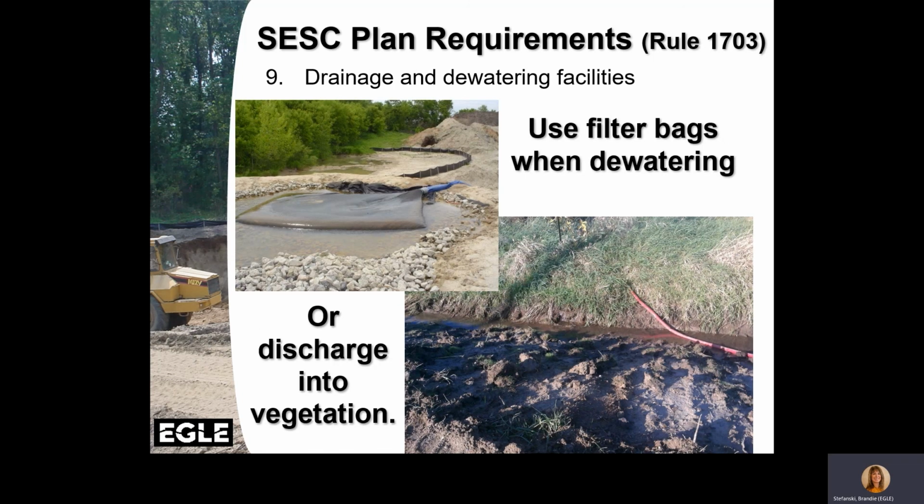Dewatering and drainage. Will there be dewatering on site? Where will the dewatering bag be placed? The SESC plans should not be approved unless the answers are known to these questions. Water needs to be filtered so that leaving the site it is not sediment laden.